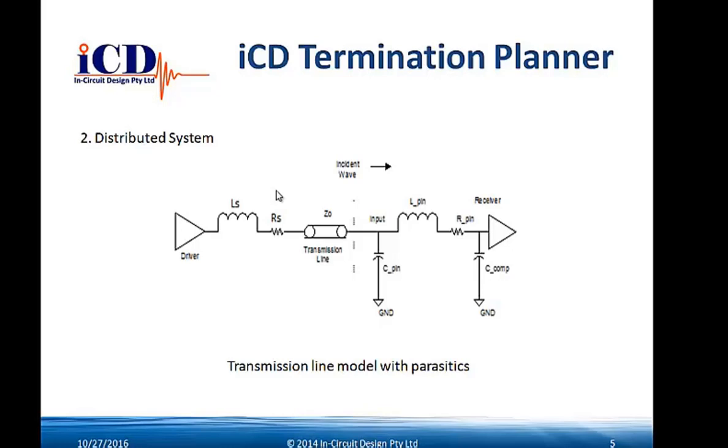And of course, the more receivers you put onto that transmission line, say if you have 3 or 4 receivers on the transmission line all driving 3 or 4 loads, then that capacitance of the component of the load is all put in parallel, which tends to roll off the signal and decrease the rise time, which is exactly what a series terminator will do. So if we put more loads onto the transmission line, then we need less series termination, basically.